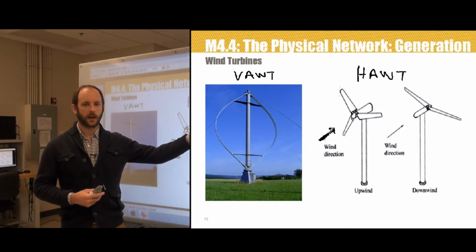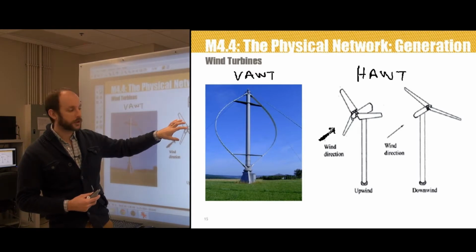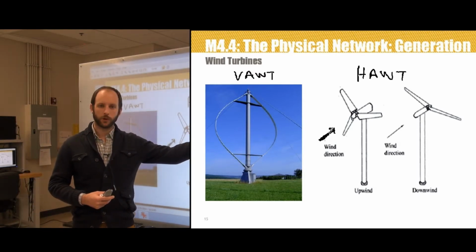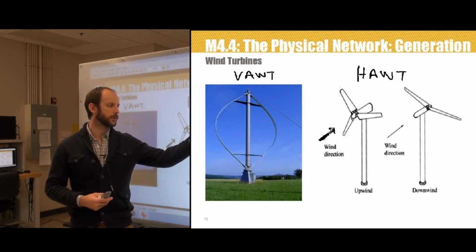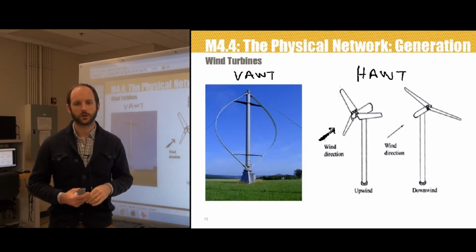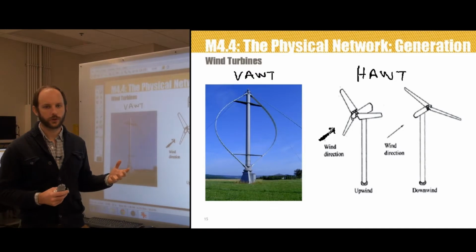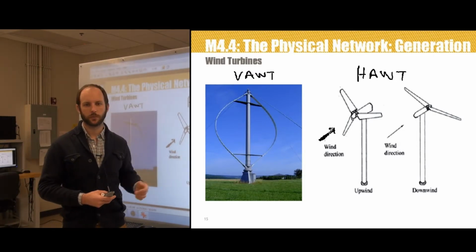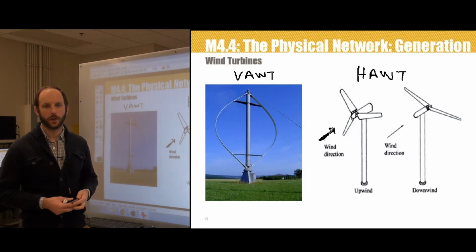Few blades, and high speed operation is physically limited by turbulence. With a low number of blades, the turbulence is reduced, therefore allowing me to spin at higher speeds. Smaller generators can therefore be used. These trade-offs have resulted in most wind turbines having either 2 to 3 blades, although I personally have actually seen a one-blade turbine construction previously.